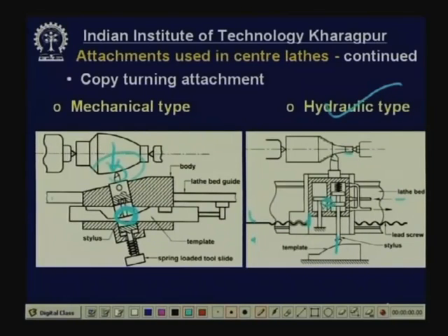As a result, the amount of port that was opened will now be closed. So, the amount of movement of the tool, delta y, will be exactly equal to the amount of downward movement delta y of the stylus. So, this will be nullified immediately, but the stylus is continuously dropping. So, again the port will open, again the cylinder will move down along with the cutting tool. This kind of movement will continue. So, this will move down, then horizontal, then vertical, like this, in the y direction and the x direction, but the roughness of the surface is very, very small. So, this will be almost linear to the naked eye.